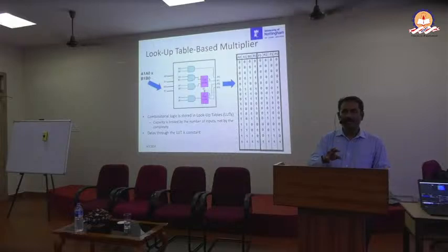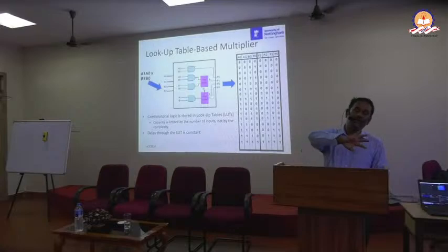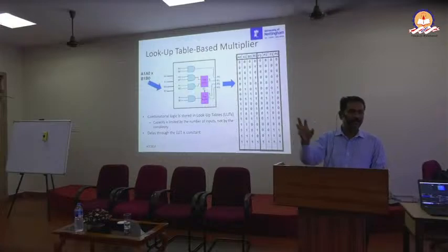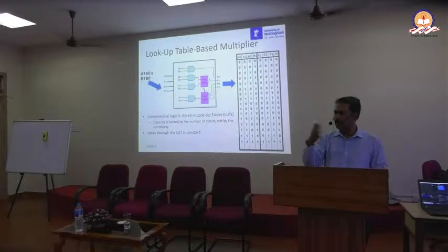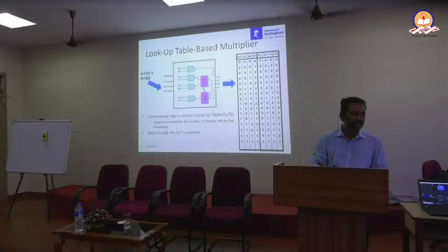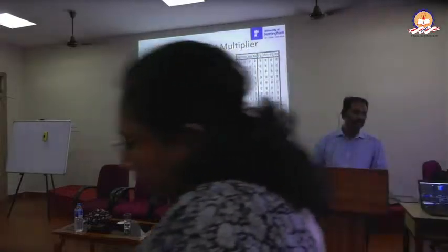So in in-memory computing, there are memory devices. That memory device is not completely going to offload your CPU work. It's going to take some of the load and give it to the memory. For instance, multiplication. Multiplication is quite commonly used in all applications, right? Image processing, DCT, you take anything. Multiplication is a basic thing, right? So you need to do a multiplication. The multiplication operation, you can actually throw it into the memory.